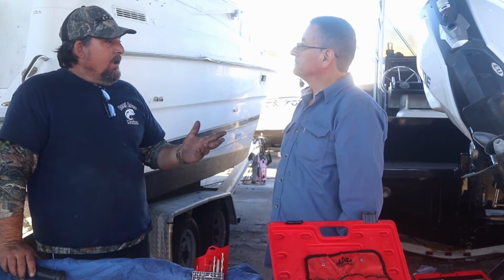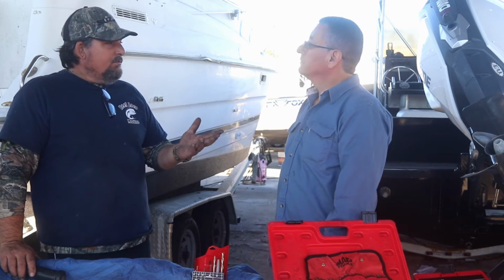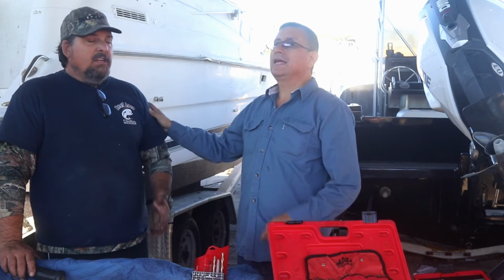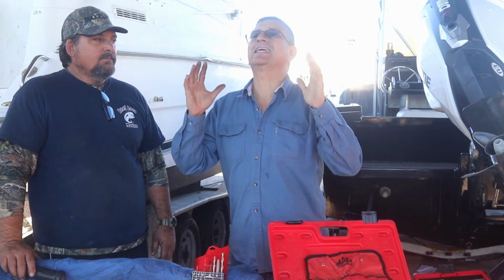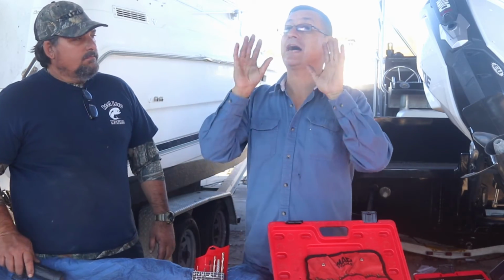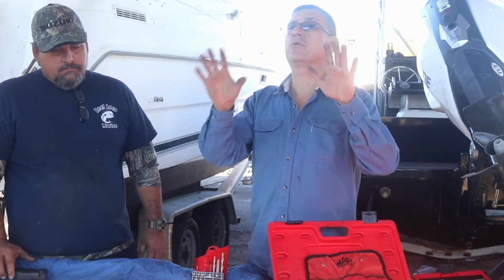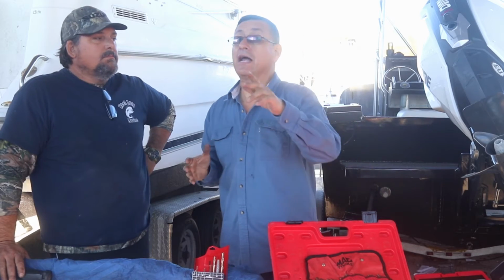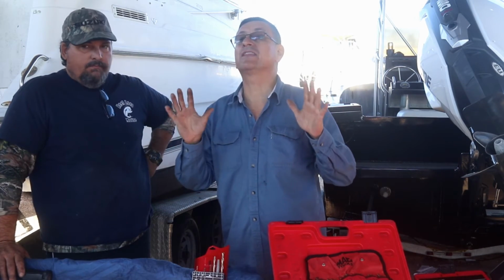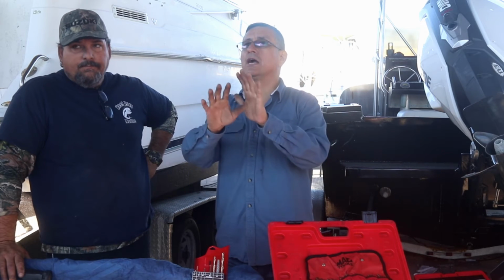And there are different grades of stainless steel, of course: 304, 316. The only one you should really use is 316 in the marine environment. Don't forget this in the future. In marine application, you need a stainless steel series 300: 304, 302, 316. All of those are accepted marine grade series stainless steel. And for the copper alloys, it is series 5000. Right. Those are the appropriate alloys.